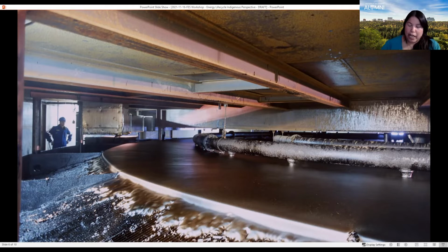And so they're really trying to capture everything that we can from this whole system, but also being thoughtful about what we're adding to the process in order to extract that bitumen. And then how do we handle those types of products? So for that middlings stream, there's a lot of research into how you can extract it. Can you do that through chemical froth treatment? Is it through more mechanical means? Is it through flotation columns? Is it through different mechanisms of aeration, perhaps? Different ways of coalescing the droplets together in order to change the chemistry, in order to extract the extra bitumen that's in there.